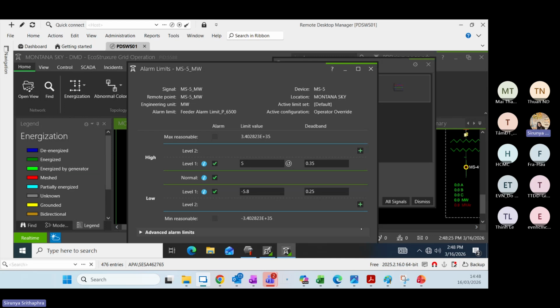Positive and negative. We can have positive and negative, and the user can override. We have some fixed data in the database. And yeah, for example, if that value goes above 5 megawatts, it tries to put some generation in to reduce that, right? And if it goes too much reverse flow, it could be any value, then for example it stops the generation, curtails the generation.